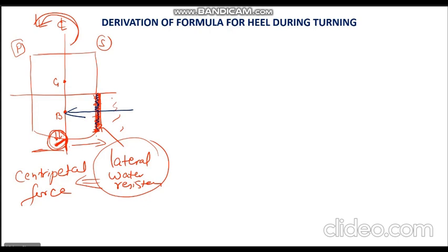Sir, can you repeat the last paragraph once more? Which force? The centripetal force, which acts towards the center of the turn, through the centroid of the lateral underwater area on the opposite side, is assumed to be acting through the center of buoyancy. Okay?